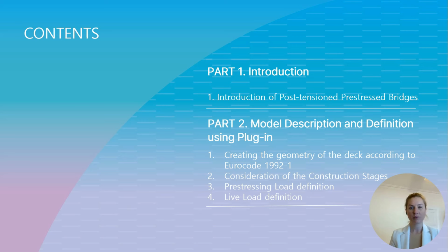It will be a simple beam, however it's curved. Let's see what the new generation of MIDAS Civil will offer us to work with curvature. The stages of making the model will include creating the cross-section and creating time-dependent material properties. Next, I will show the loads. These are permanent loads, pre-stressing loads, and again how to cope with the curvature in terms of pre-stressing. And we will have a look at temporary loads.